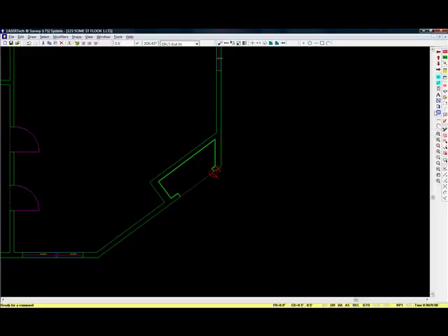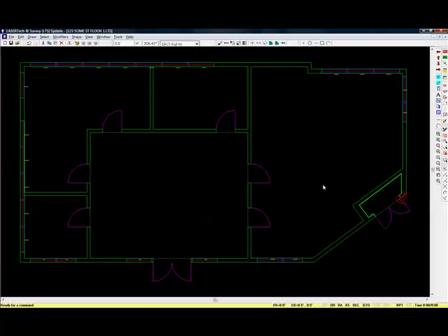Now we just want to put in these double doors, and another way to put in a set of double doors, I'll show you this way. We could put the hinge point there, and for the striker point we're going to say it's the midpoint of this tracking line. So we have a snap midpoint, and then we just place the door. Now we repeat and we say hinge, striker. We have a point there now, and there's our set of double doors. So we could have placed the symbol or placed them individually, either way.